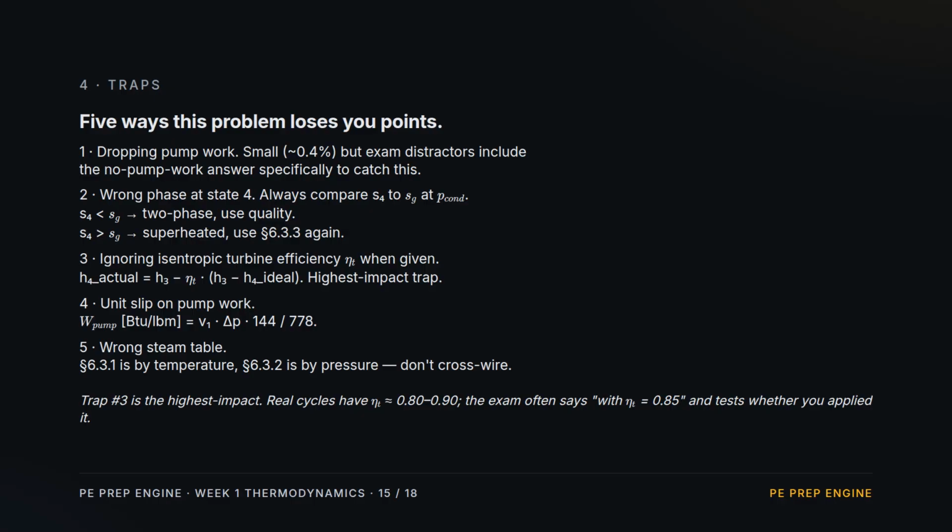4. Watch the pump work conversions, 144 and 778. Get sloppy and you're off by 100-fold. 5. Keep the temperature indexed and pressure indexed saturation tables straight, and don't crosswire under exam pressure.